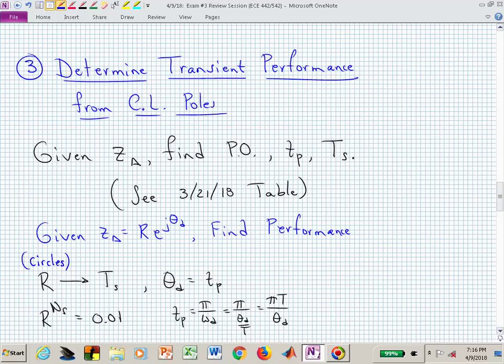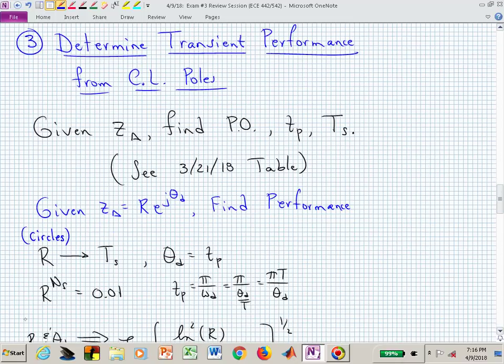That allows you to derive the settling time, T sub s, because you can solve for N sub s if needed. N sub s is now this minus 2 over log base 10 of r, sort of this ceiling function on that. You take the smallest integer above some value, and that's now N sub s.